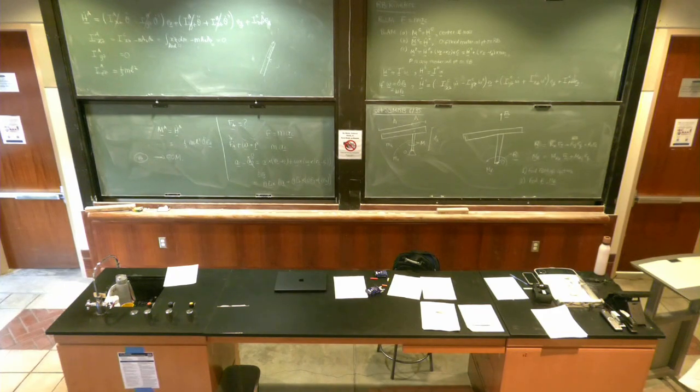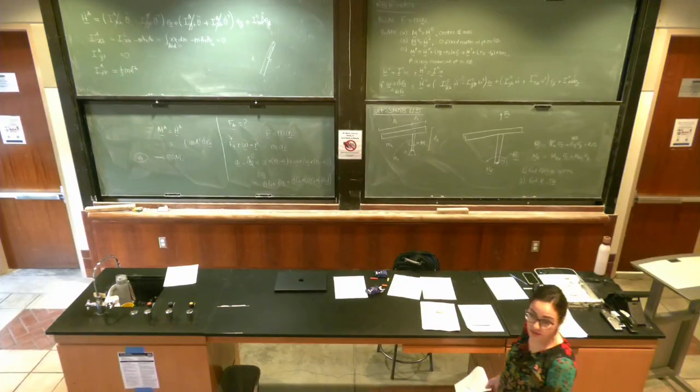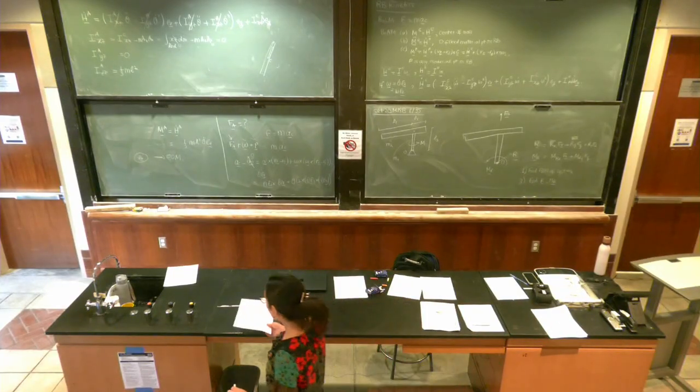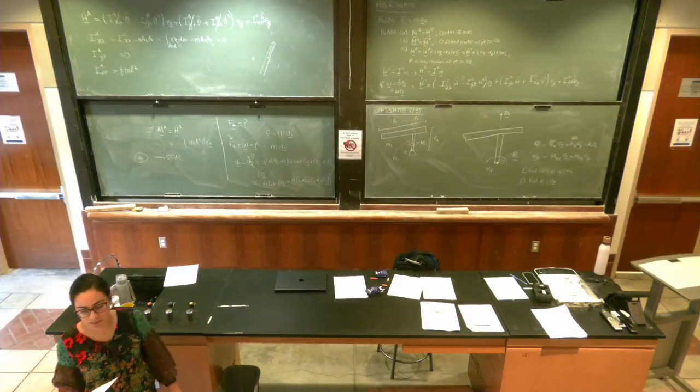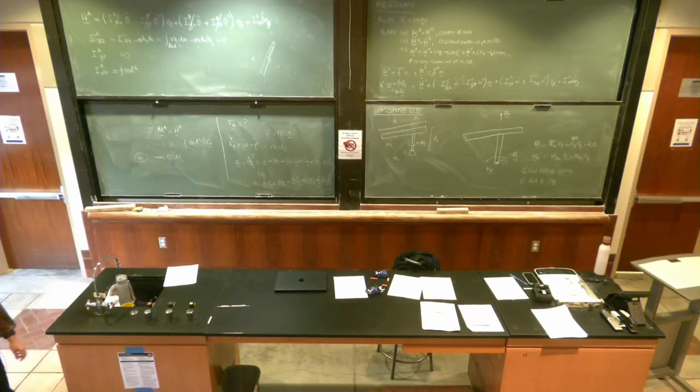So let's go ahead, work in groups of 2 or 3. Find the balance of angular momentum. Step 1, calculate the balance of angular momentum about O. And be careful, not all the products of inertia are going to be 0. So you're going to have non-zero products of inertia. So go ahead, do it, and I'm here to help. Let's give like 10-15 minutes for this first task, then some time for the other task, okay? It's very important that we work on this together.